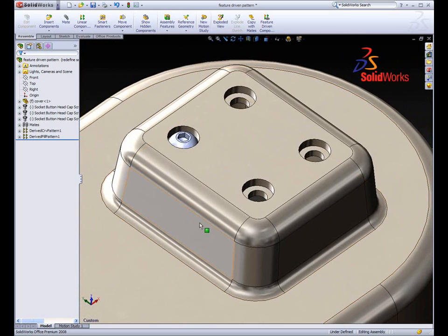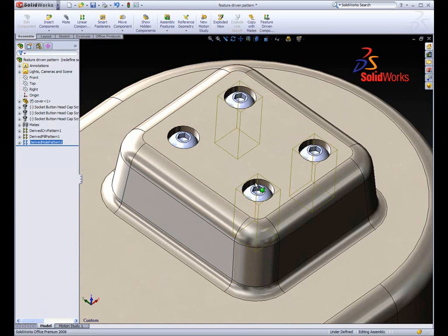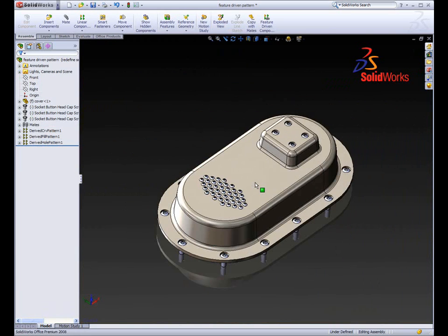The intelligence of SolidWorks even goes a little further. Here you can see I have 4 holes. They were not defined with a rectangular pattern. It's simply a multi-hole location, one Hole Wizard feature with 4 locations. And as you can see, SolidWorks still puts the screws in the correct position.